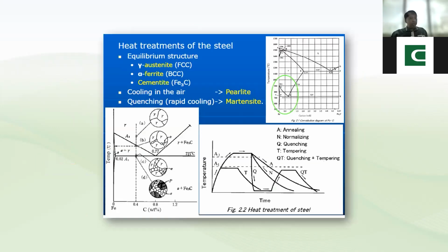So these are the summarized portions of your different heat treatments, no? So the first one, please follow my pointer. Slow heating, soak at 600, and ang bagal ng cooling down. This one is annealing.